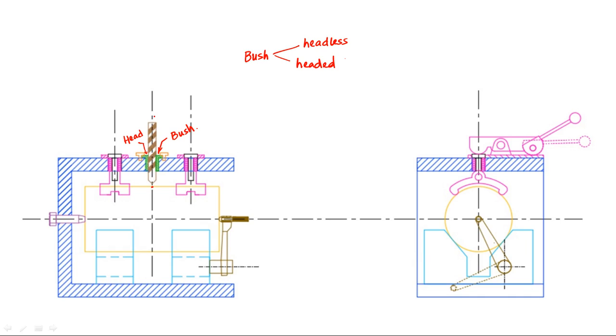Now to eliminate that chance, what we can do is use a pin. These are the pins. We can use pins that will hold the bush at its position, so even when we take the drill out of the bush, it will not move or come out with the drill bit.